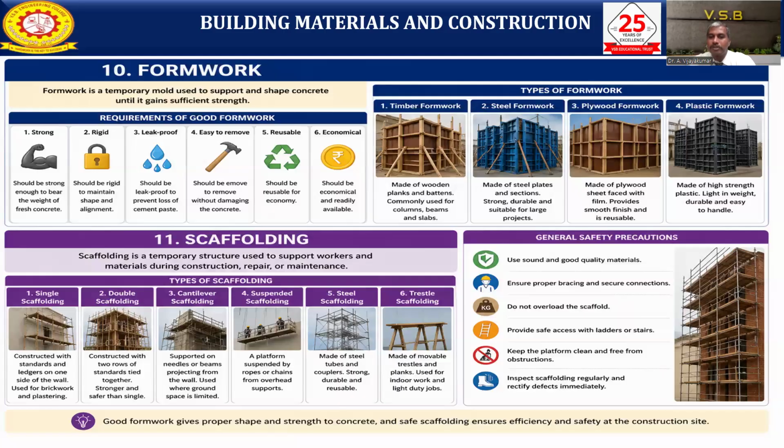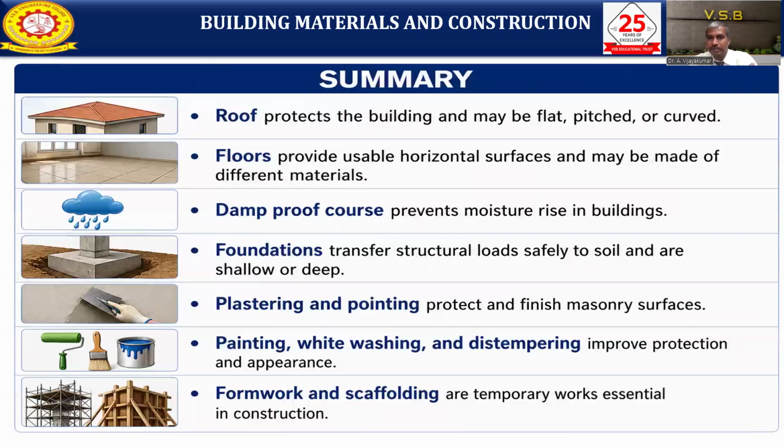Do not overload the scaffold. Provide safe access with ladders as well as stairs. Keep the platform clean and free from obstructions. Inspect the scaffolding regularly and rectify defects immediately, if anything happens in our scaffolding. Okay. So good formwork gives proper shape and strength to the concrete, and safe scaffolding ensures efficiency and safety at the construction site. So dear learners, these are the summary of this module.